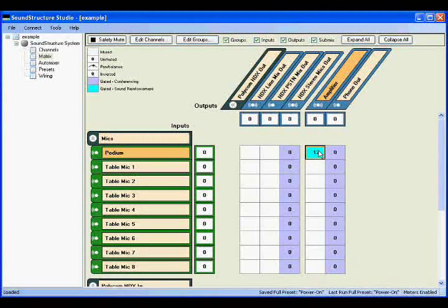the audio that's sent to the far side because both the acoustic echo canceller and the nonlinear processing will try to cancel the podium microphone audio from the signal that's picked up from the podium microphone. To fix this, we need to have a valid echo canceller reference for the podium microphone that does not have the podium microphone in it, but does contain all the remote audio that we do want to cancel. The way to do this is to create a submix that contains all the remote audio and then set that signal as the reference for the podium microphone.